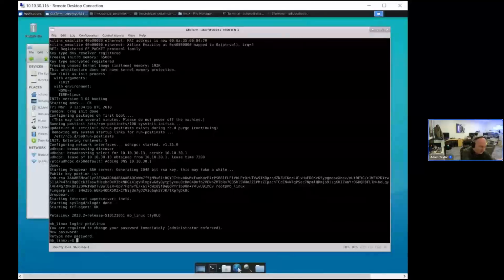Just to divert slightly, we have this board I showed at the beginning. I'm just going to disconnect it so I can wave it about a bit. This one's got a Kria on it, so it's the K26. It's a custom carrier card that we designed. It's got an Ethernet on it, and the Ethernet clock is generated by a Skyworks chip, would you believe. You need to program the Skyworks chip to generate the reference clock for the Ethernet to come to life.